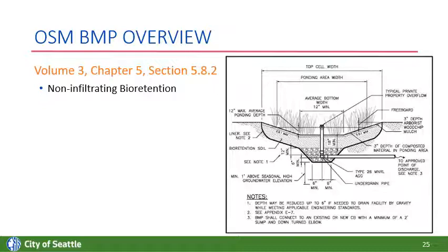The liner can be omitted if the horizontal setbacks are met and there are no geotechnical or contamination concerns. So even though infiltration is not feasible for the site, the liner could be eliminated as long as there are no adjacent steep slopes that are of concern and you're maintaining setbacks from buildings.